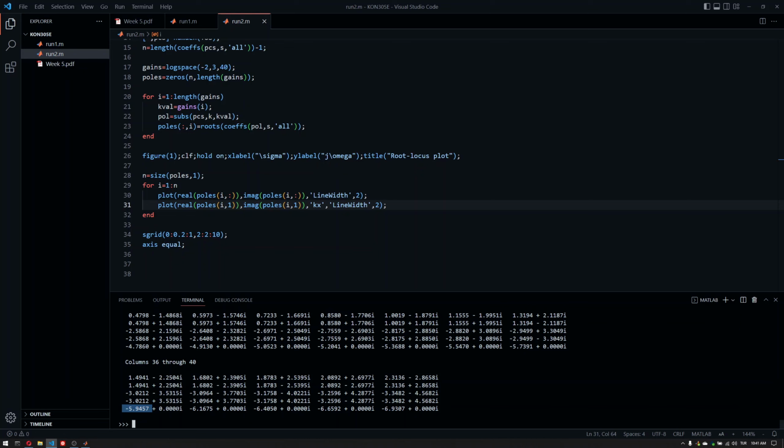Which is actually the next value for this pole out of these poles here? Luckily, if it's a real value, you can see it is -5.94, and then this is -6. So this is correct in this path here. You can see -6, it's always correct here. But the complex conjugates may mess this up as it is now.